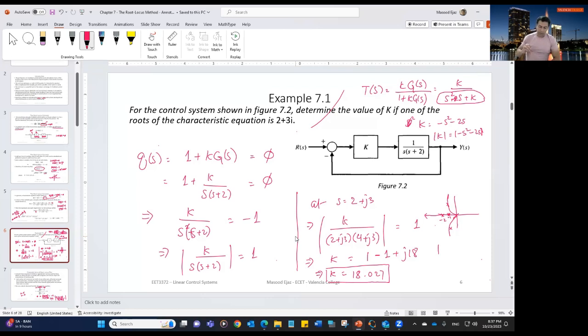So all those things that you're designing for a control system come from poles. So if you're designing for a specific gain of the control system that is producing a specific set of roots, that will determine the response of your system. The speed of the system, transient decay of the system, sustained value, and all those things.